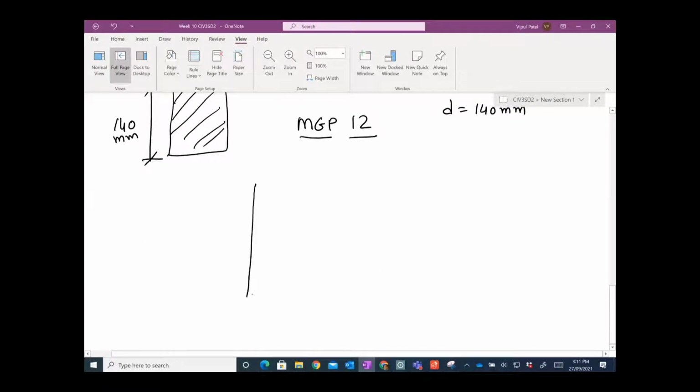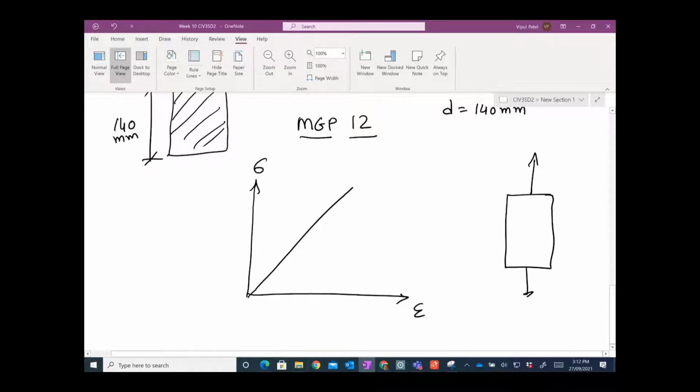So if you test the timber beam under tension, and you just pull it and draw this line, the elastic one, then you know how much load you are applying, right? Let's say this is the timber that you are applying it to. This load over area will give you the stress. You can record that value, and how much it's going to extend.